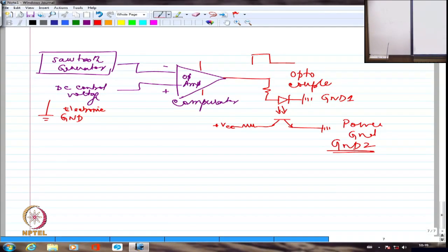So generally in 99% of BJT, IGBT, MOSFET applications, we have to use optocouplers. Right? This optocoupler essentially makes sure that the pulse is transmitted from one side to the other side without really having any electrical connectivity. So the grounds become completely isolated. Now whatever is available across this resistance will be exactly the same pulse. Right?